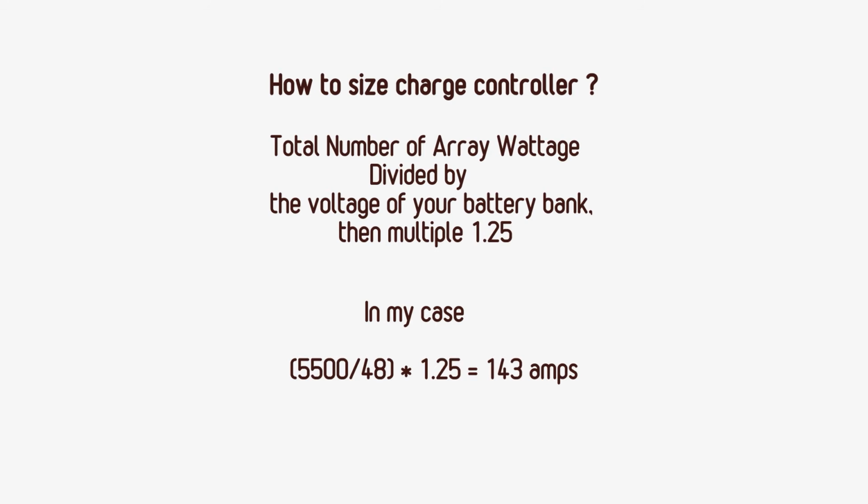If you have your charge controller and your inverter all in one box, when that box goes, your solar productivity is just down the tubes. But if you separate them out, if you have a failure in one part of your system, your blast radius is much smaller.